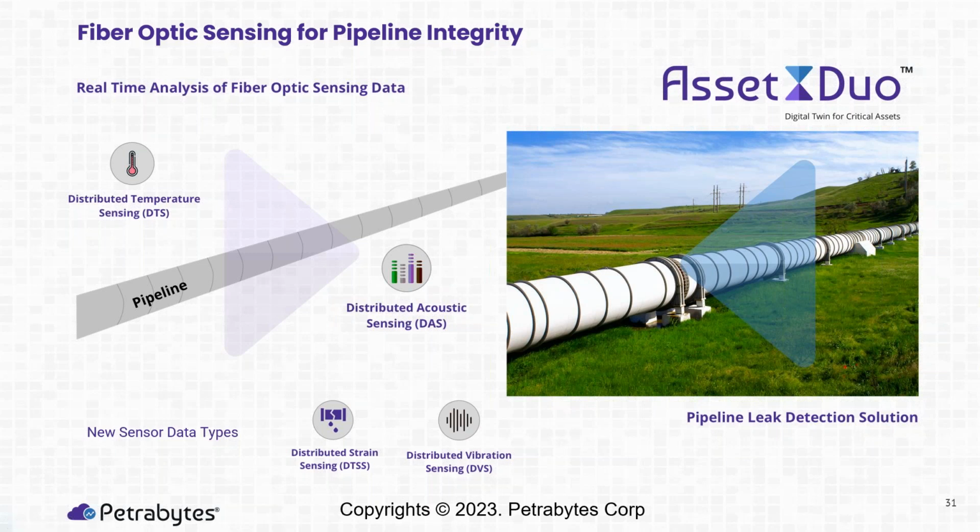So this needs to be combined with the ILI risk modeling that typically people do, because that is more like a static model. It's not dynamic until you rerun, right? But combining that, let us say on an ILI model, you have identified there is a potential risk of failure on a particular pipeline, then you would go into the SCADA systems or this kind of sensing to look for more accurate monitoring on a timely basis. So this is more like real-time monitoring.